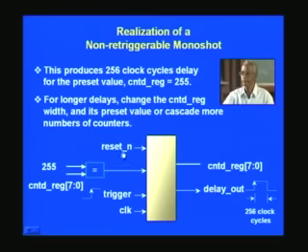And once again you have a synchronous reset, and this time I have put D, because what all we have learnt, we are going to put together in a single program and then execute. If you just give the same name, it will be overwritten, so I am deliberately putting a different name. So here D stands for that, and this is 8-bit, and that's a trigger applied here, and this is non-retriggerable. That means once you have triggered, the delay starts. Any amount of further triggering will not really have any effect. So that is the idea here, and that's naturally a clock, and let us see how to code it.